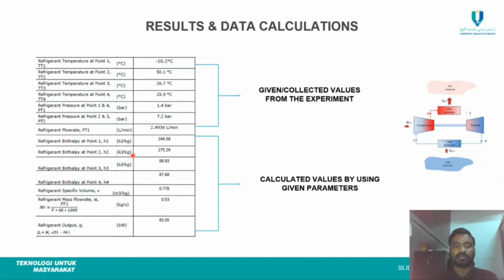So in order to find the enthalpy at the 4 points, we need to refer to table A11 in the property tables to find the values. Since the values are not directly in the table, we need to use the interpolation method to find the enthalpy at each point.